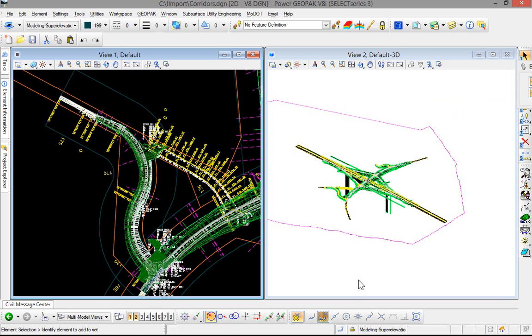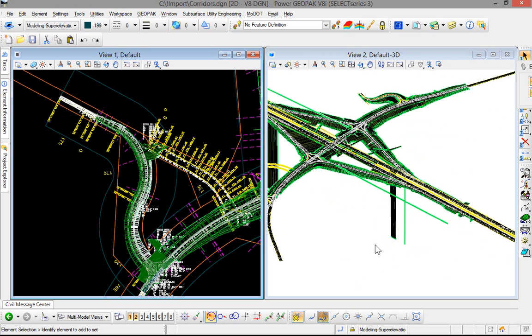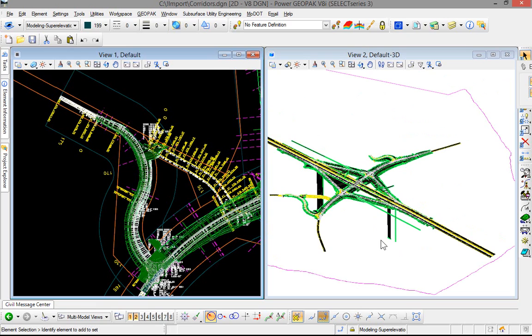With all the corridors now imported and our dependency reports created, we're ready to begin to correct or add in the references that each of the corridors are missing. And you can see over in our model we have, for example, because we're missing some alignments, tie slopes going down to elevation of 0, that type of thing. And so all of this will become cleaned up when we start adding in our style constraint targets and our target aliasing, as well as our point control information.